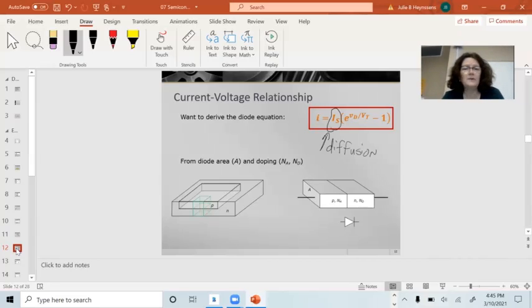If you go to a diode data sheet, they will have IS on there. If you're the guys building the diode, you have to think about what influences IS and come up with ways to minimize it as you need to. And then it gets exponentially larger when I get into forward bias.